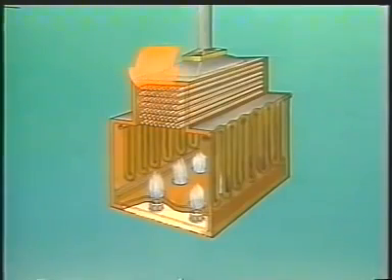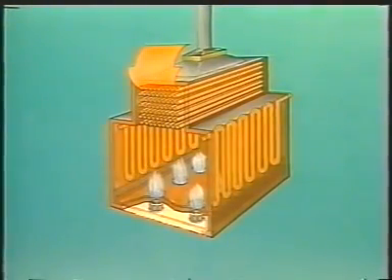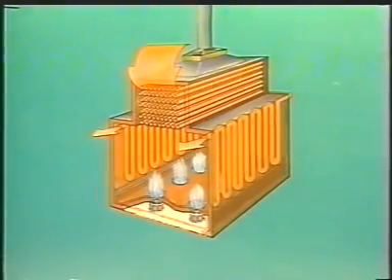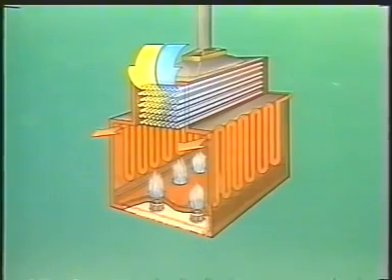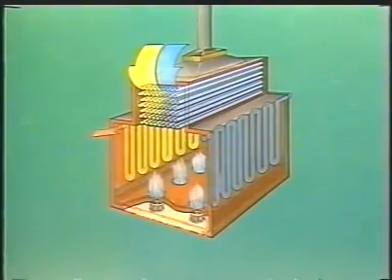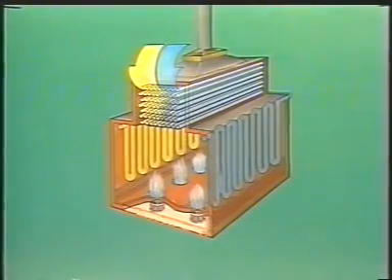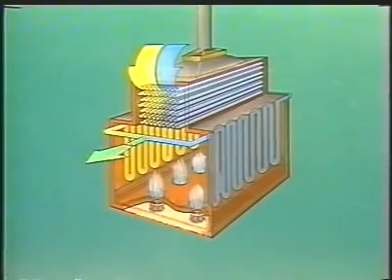The process flow is sent through the tubes and is quickly heated. It then flows out of the furnace to other process equipment. The tubes which carry the process flow are generally divided into passes or coils. If the passes are balanced properly, each pass receives the same amount of process flow and absorbs the same amount of heat. After the process flow is circulated through the passes, it is rejoined at the outlet.